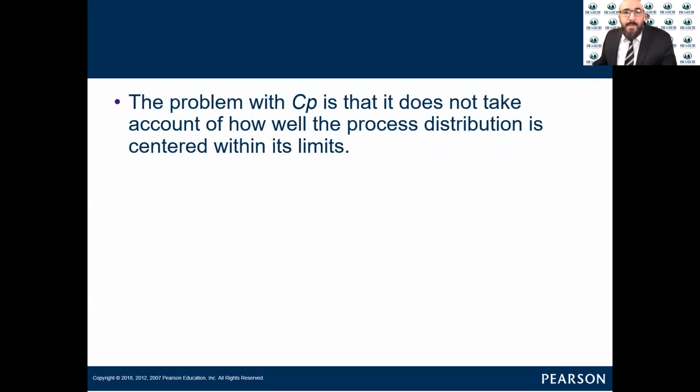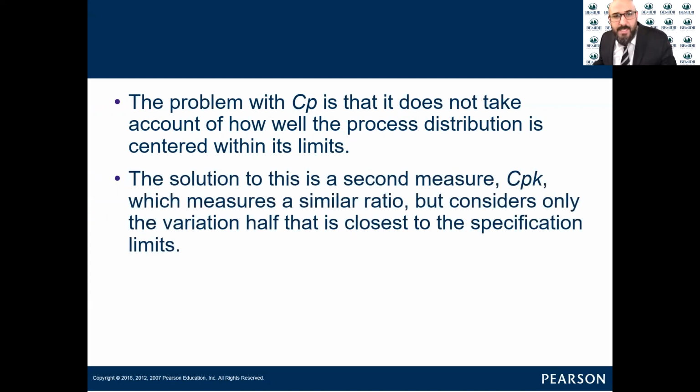Okay, the problem with CP is that it does not take into account how the process is distributed. So the process could be capable, but we don't look into the distribution. We don't know if the process is centered or not. And it is important to look into the process distribution and whether it's centered or not.